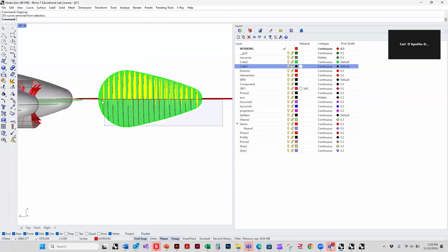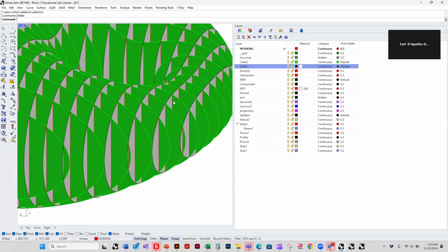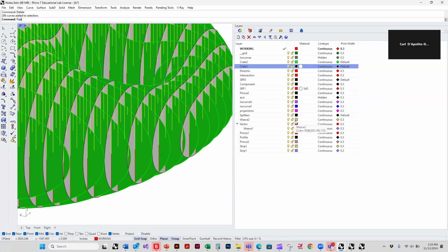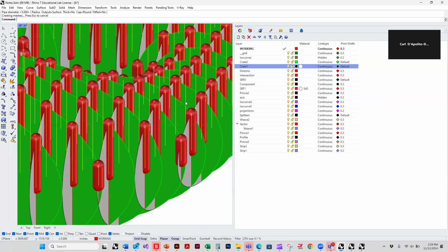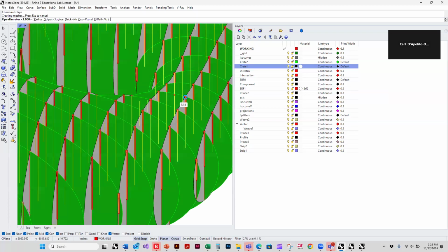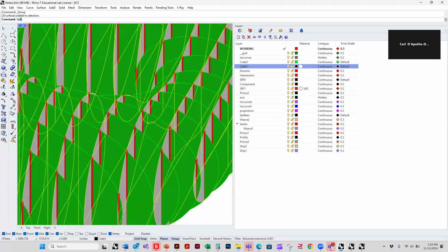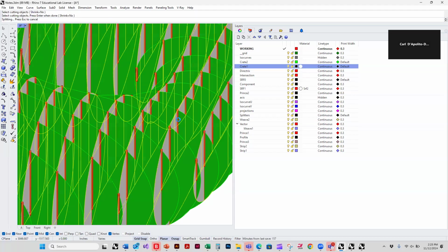And then what I always do to intersect two surfaces rather than building the thickness is I pipe them with the thickness of the material as the diameter. So half of the thickness of the material as the radius. And then I split the top half out of one set of surfaces.